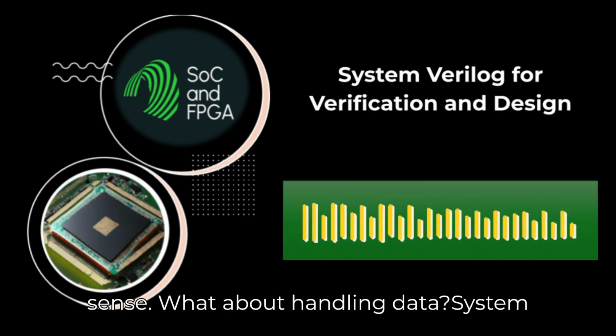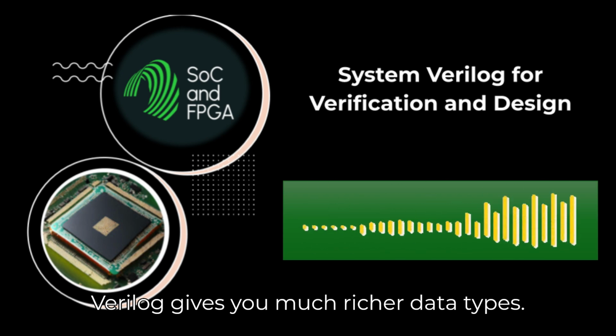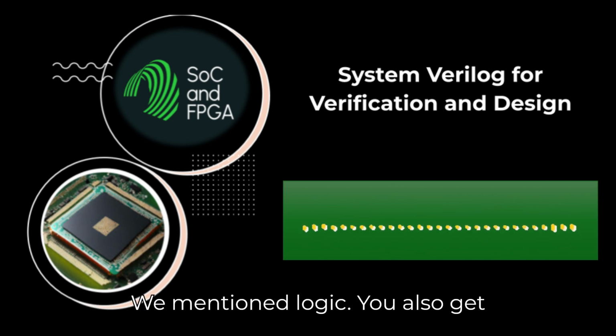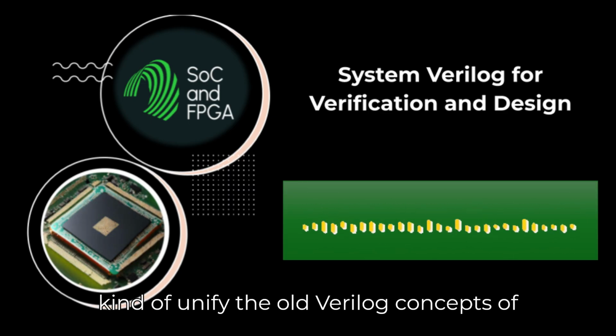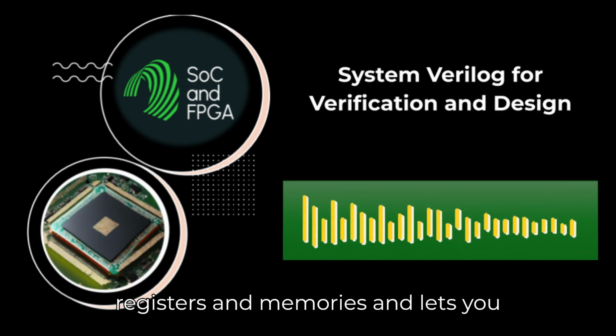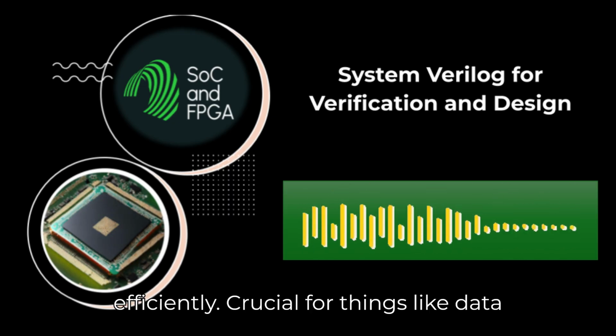Makes sense. What about handling data? SystemVerilog gives you much richer data types. We mentioned logic. You also get multi-dimensional packed arrays. These kind of unify the old Verilog concepts of registers and memories and let you manipulate blocks of bits really efficiently. Crucial for things like data paths.